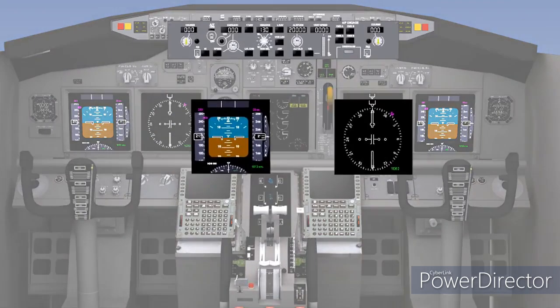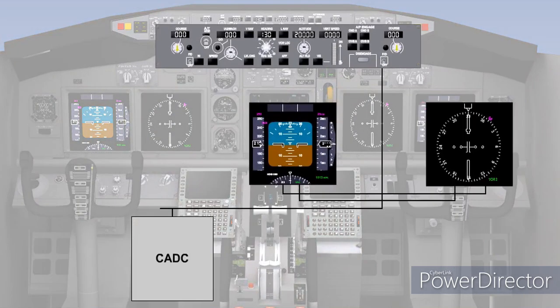To use the guidance functions of the autopilot for long-term navigation and speed control, the autopilot needs to have current navigation and air data information fed into the computer. When the respective pitch or roll command mode is engaged, the computer couples the target value with the current value to generate a steering command to the inner loop.